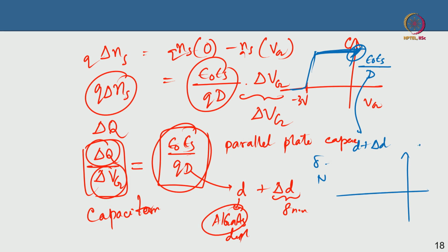So if you plot the capacitance versus gate voltage, I already told you, if your pinch off is say -3 volt, then it will look almost like a rectangle from -3 to 0 volt. Okay. So this is basically a flat capacitance, it is a parallel plate capacitor and the capacitance does not change with the gate bias, and the area under this CV profile from say pinch off to 0 volt will give you the 2D electron gas concentration under the gate at 0 volt.